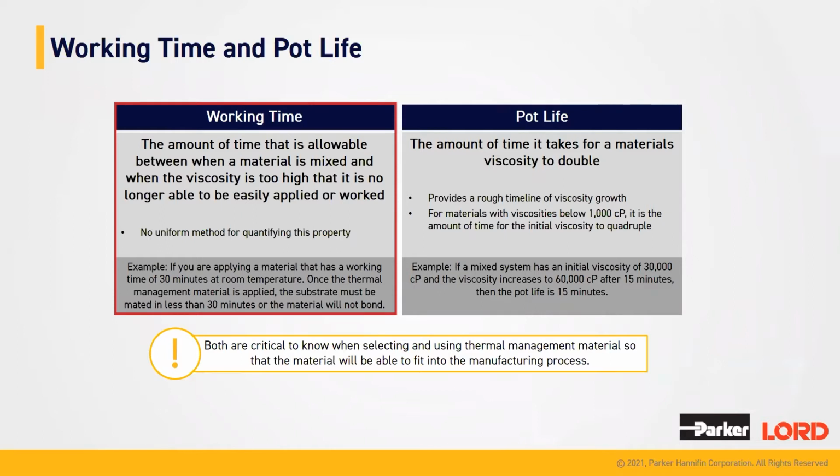So an example of this is if a material is rated for a working time of 30 minutes at room temperature, and once that material that has a 30-minute working time is applied, the substrate must be mated in less than 30 minutes, or if you wait longer, the material will no longer bond properly.